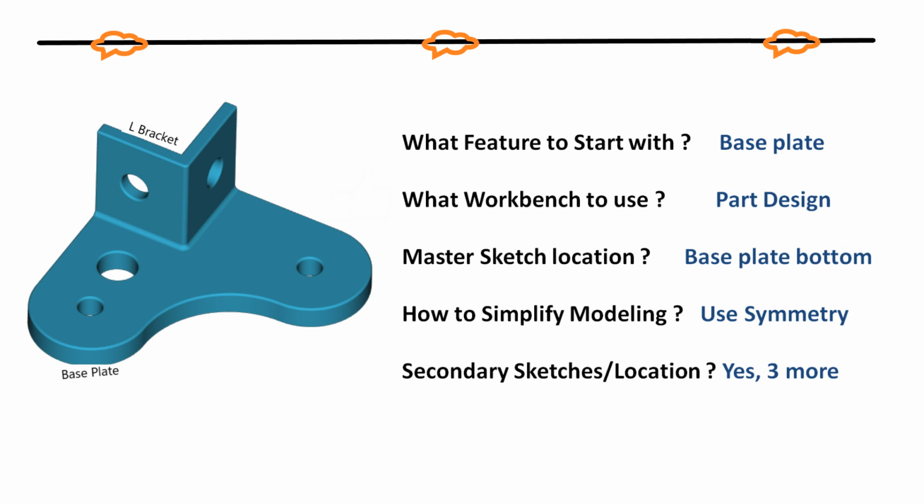What workbench are you going to use here? Since modeling this shape with the Part workbench primitives is going to be inefficient, use the Part Design workbench. Start with a sketch and pad it. If you're not familiar with the Part and Part Design workbenches, I would recommend watching one of my previous tutorials on this topic. Links will be in the description.